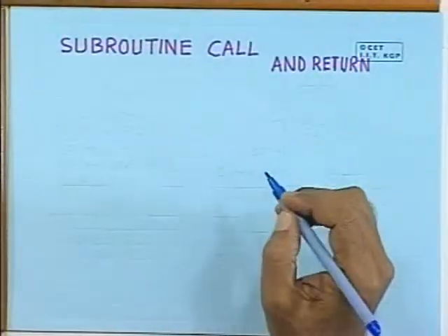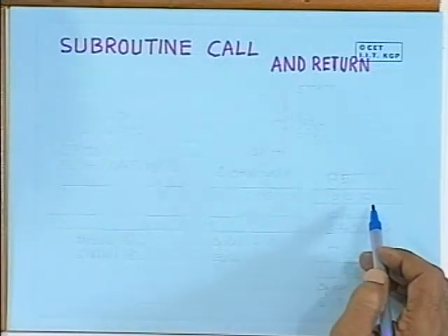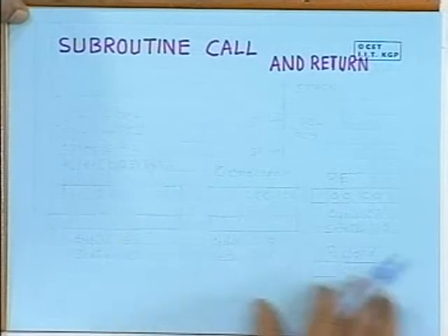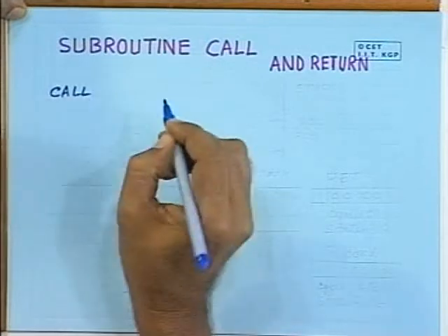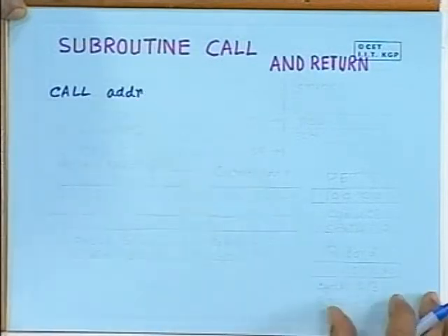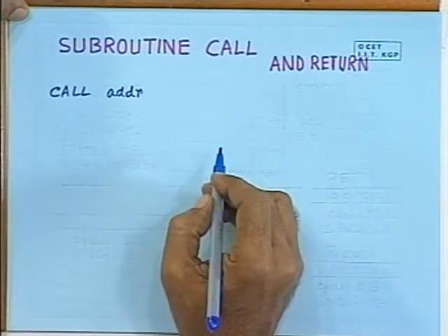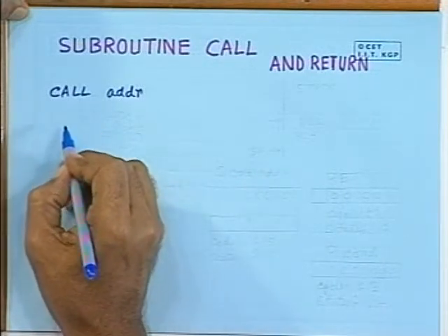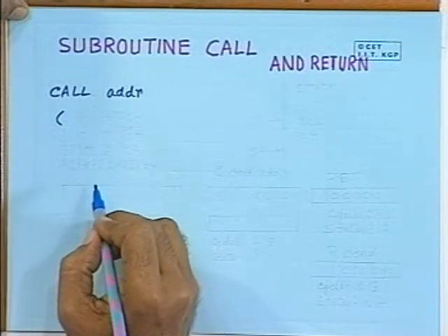Now, whenever you are writing a program in a modular fashion, obviously you will write a main program, you will also write some subroutines, and to facilitate that, there is a facility for subroutine call and return instructions. The basic code is CALL ADDR. This is the mnemonic of the instruction. Whenever you perform a subroutine call, you have to load the program counter with some new value.